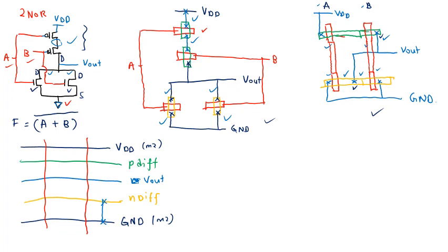This is metal 2 and metal 1 here, since they are different metals, I just put a contact like this. And then we have both the drain sides connected to the output. This is output, and this is the N diffusion side, and both should be connected to the V out, right? So you need to put the contact in the middle. So this is the contact.